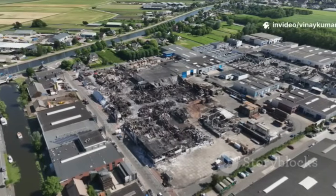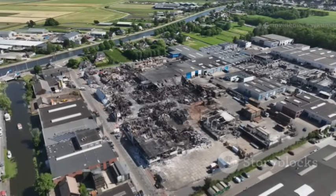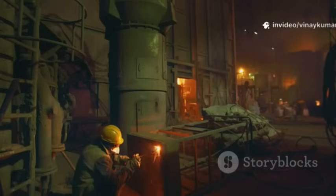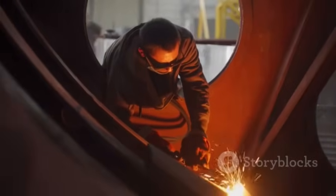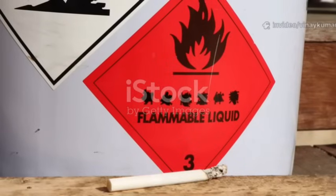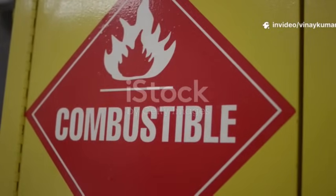Some of the most devastating industrial accidents have been caused by a seemingly simple combination, a flammable chemical and an ignition source. Our sixth element, hot work permits, is designed to strictly control one of the most common and dangerous ignition sources, open flames or spark-producing activities. Hot work includes things like welding, brazing, cutting, and grinding. Performing these activities in an area where flammable gases or vapors could be present is like lighting a match in a room full of gasoline fumes.